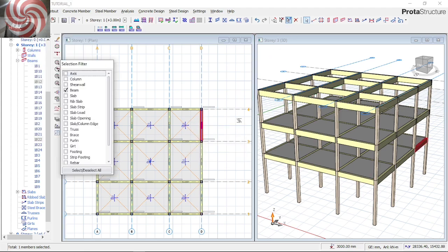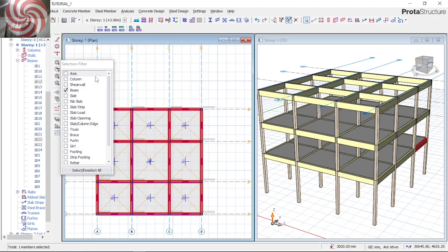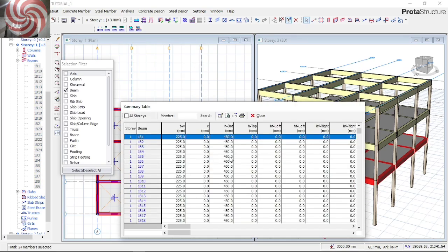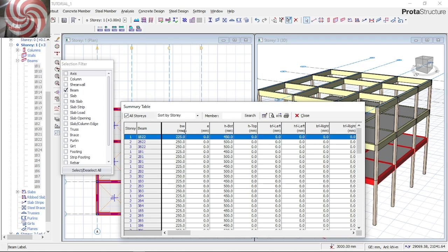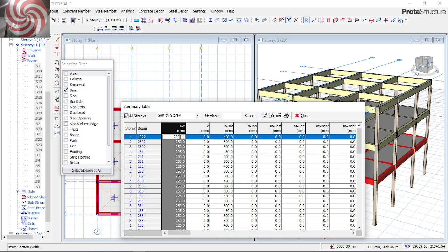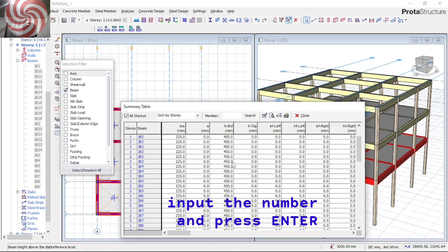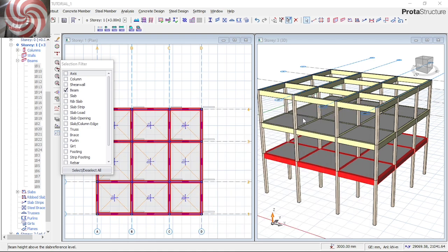So I come here, I deselect again only the particular beam. And then I click all stories widths. I click 225. Then this one write 450. Alright, that means this effect is affecting all the stories. Now I'm done with that.